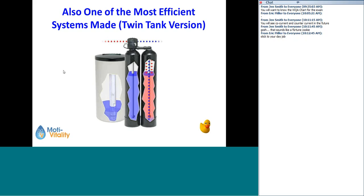Think about this. If you're regenerating with hard water, my King of the Hill example, remember the sodium, they called up all their sodium friends to come in and kick the calcium and iron off that resin bead. Well, if you're regenerating with hard water, then in with the sodium, you've got a bunch of calcium and iron spies, right? And so the sodium not only has to fight against the calcium and iron that's on the resin bead, but also the calcium and iron that's in the water that it came in with. So it takes even more sodium when you're with a single tank softener to clean in hard water.